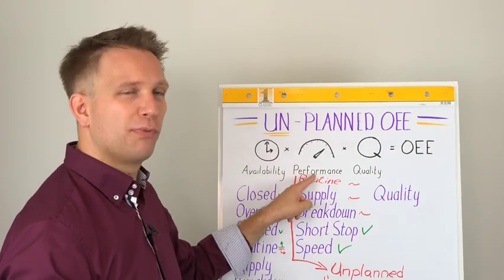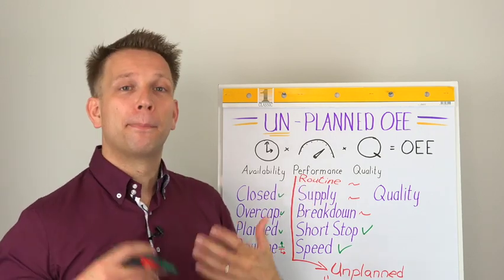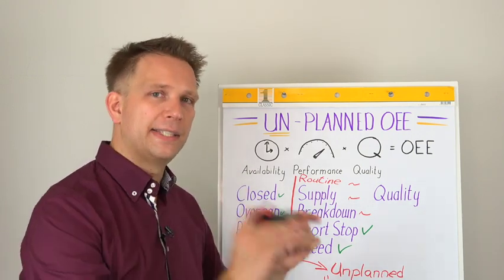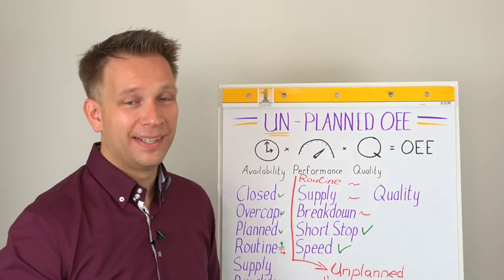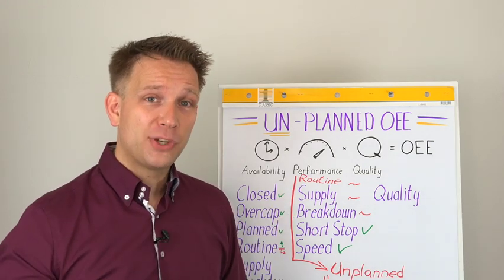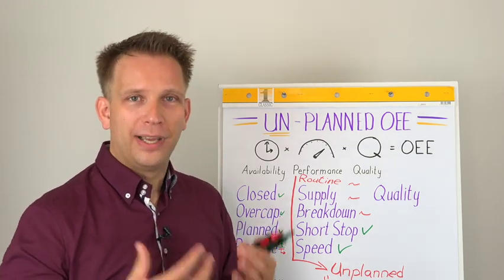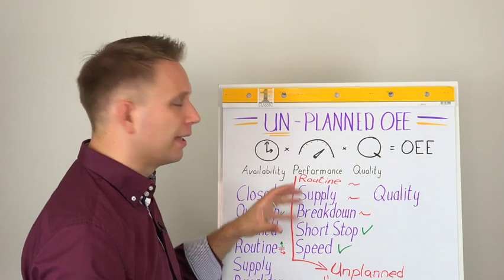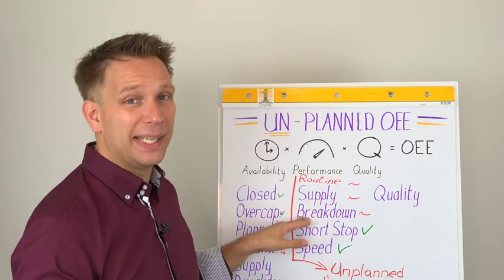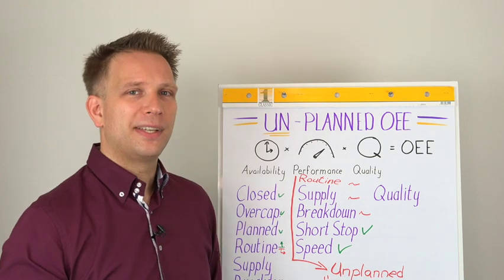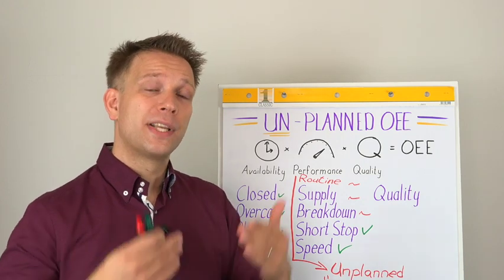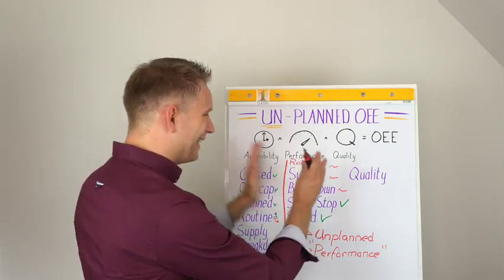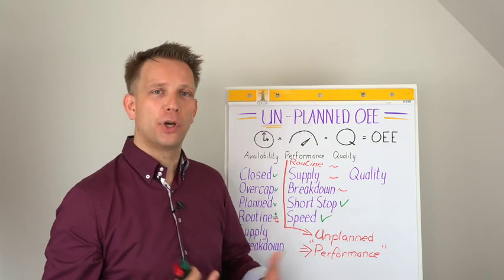So not just the performance in our regular OEE, but the planned or the unplanned, let's say, performance number, that has to be 10, 20% higher than our bottleneck line. And that is very important, because especially those lines that are not our bottleneck line usually do not get the same amount of attention for these supply routine problems, and sometimes they even get less maintenance attention. So also these breakdown percentages play a much bigger role with these down the line machines. So when you're in a planning department, take this type of unplanned performance OEE into account.